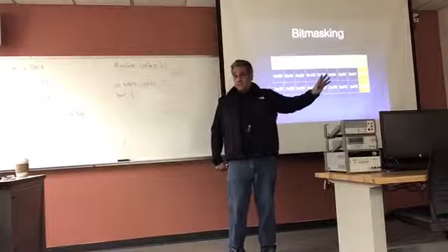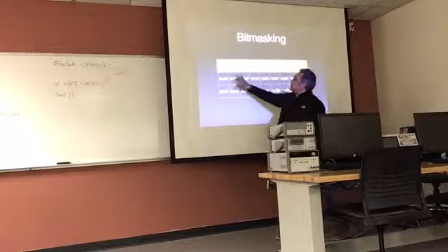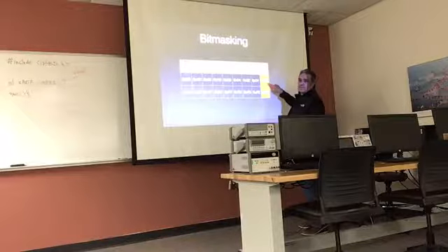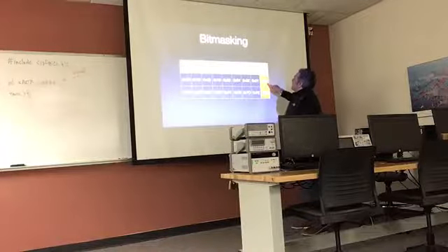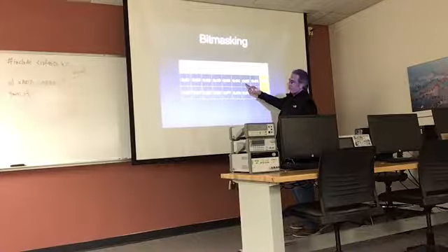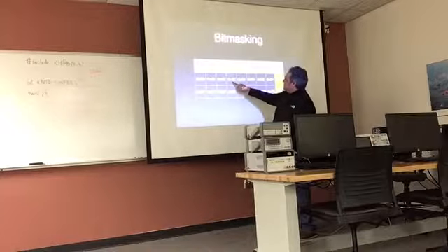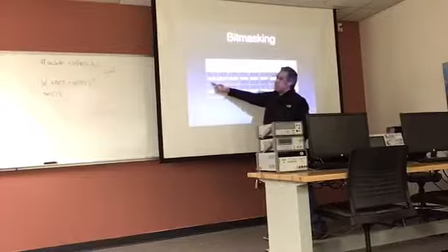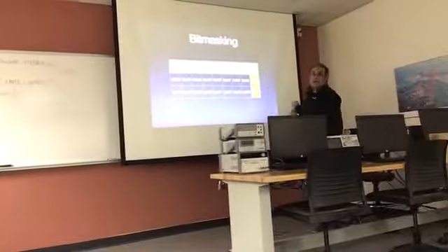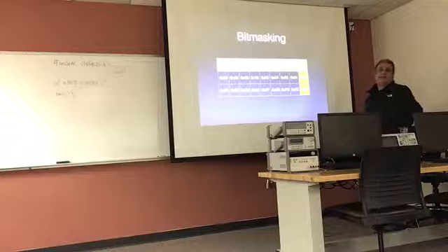So here we go. There's a cheat sheet for you. Talking about positive bit masking, this table is going to show you how to access the 0 bit if you're using a positive mask. If you want to access the 1 bit with a positive mask, that's the mask that you need. That's the 2 bit, that's the 3 bit, the 4th, the 5th, the 6th, and then the most significant 7th bit. All right? This little table, I carried it with me forever, and as time went by, I remember these numbers from the top of my head.